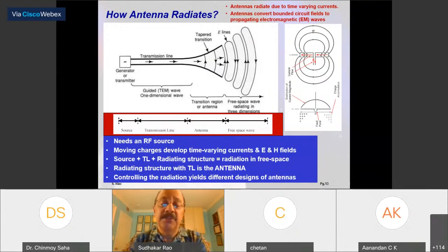Typically, we design these systems including transmission lines, everything. We design antennas with 25 dB return loss, not 10 dB. Typical specs over temperature are about 20-22 dB. So to make that by design, you need to show at least 25 dB return loss. This includes not just the antenna, but the feed assembly, the reflector, components like polarizers, filters, diplexers, and the waveguides, etc. All these things need to be included when you design the system. We design these components, but then we need to integrate them and do the integrated design. Then only you can finalize.